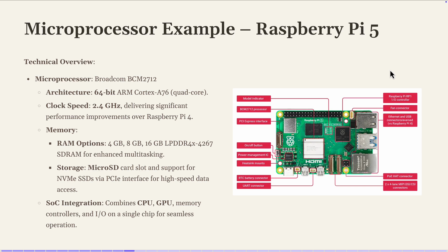And the added value of Raspberry Pi over the previous ones is that it has an integrated GPU along with the CPU into this system on chip. Okay, it has a SoC integration which combines both a CPU and a GPU. But of course, this GPU is not the same as the GPUs for gaming. It can improve, for example, the video execution performance, but it could be limited for AI algorithms. For example, if you want to run YOLO algorithms or object detection, it can work. It will provide better performance, but still it's not at the level of non-edge devices.